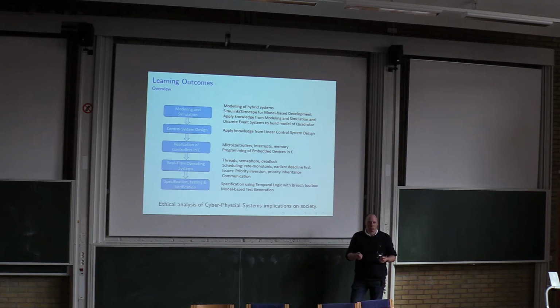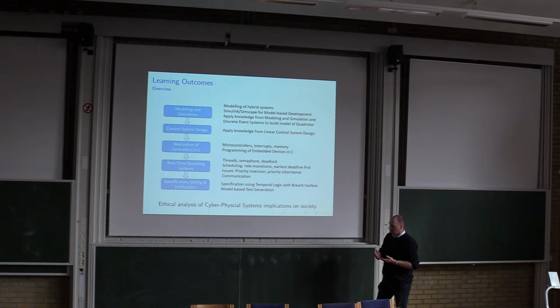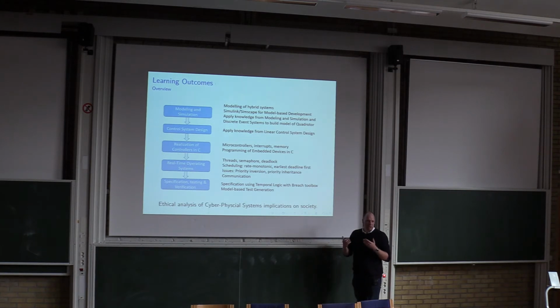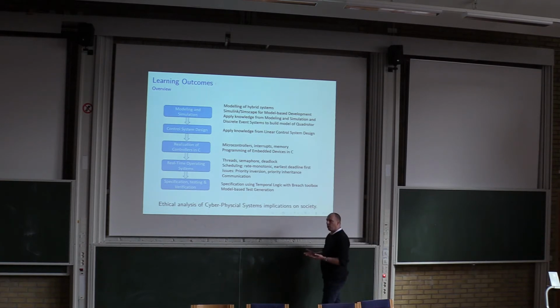So you will design an LQ controller for this rotor, and then you will do two different things. You will generate the code from these tools. We will use Simulink and the embedded controller toolbox that will generate the C code for you automatically, so you can quickly get started and see some results. But when you have done that, at the end of the course we will also talk about what's going on under the hood.